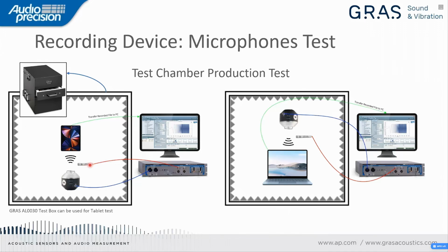In this case, the microphone inside the chamber could be a quarter-inch microphone if we have problems with space. It can be used not only for equalizing the mouth simulator, but it could be used, for example, to test the noise floor inside the chamber.